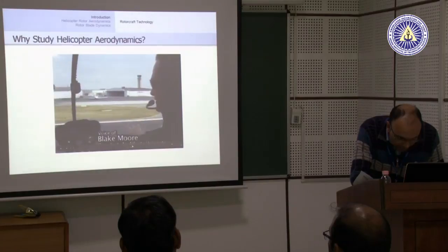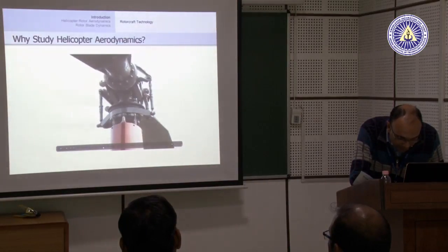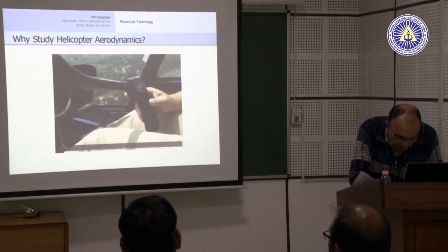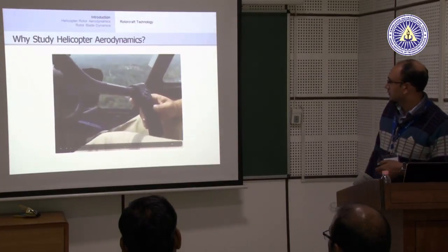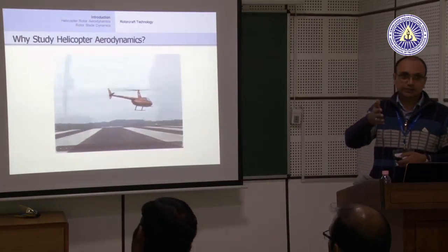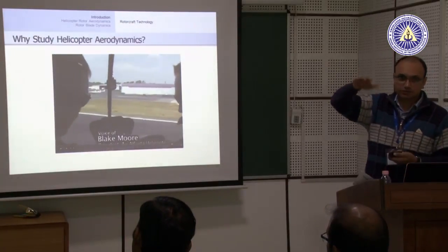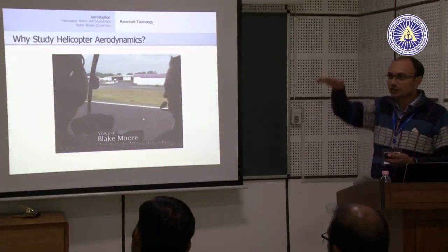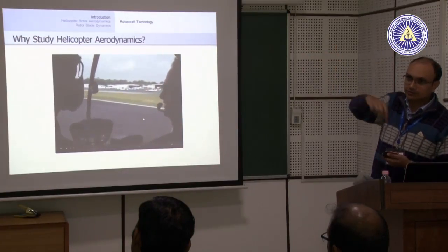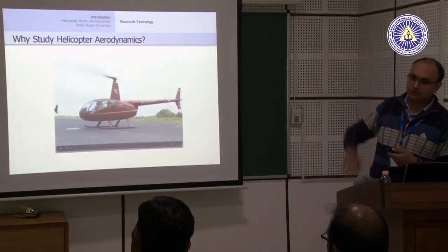In between he had talked about the cyclic control. Let me go to that. Where is the cyclic? That is collective. Yes, so here is the cyclic stick. When he moves the cyclic stick, that tilts the rotor tip path plane in a particular direction. So if I move the stick left, my rotor will tilt towards the left. Similarly, if I tilt it to the right, it will tilt towards the right.